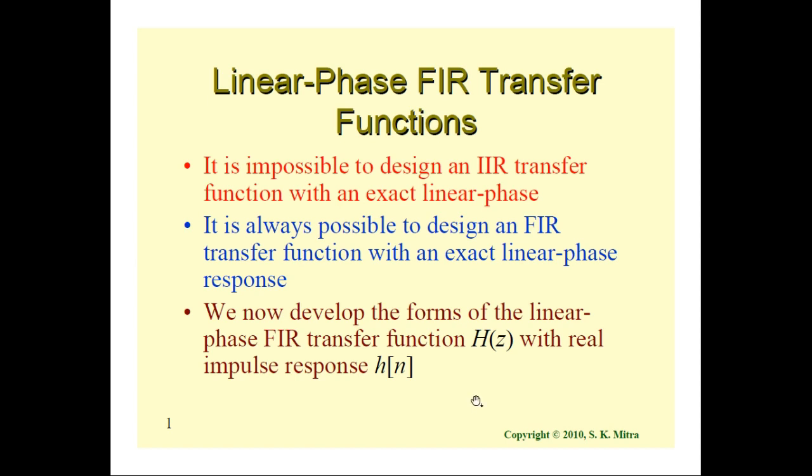linear phase. Though we developed a solution where we cascaded the IIR filter with an appropriate order all-pass filter, all-pass system, to have linear phase characteristics. But here we are specifically talking about only a single filter where we don't do any cascading. So in that context, an IIR transfer function cannot have exact linear phase. However, it is always possible to design an FIR transfer function with an exact linear phase response.